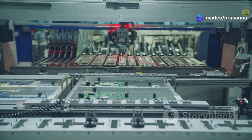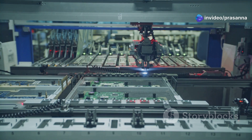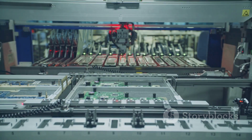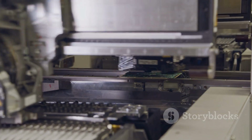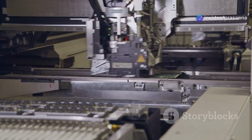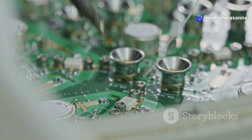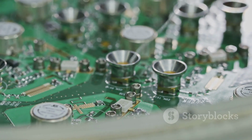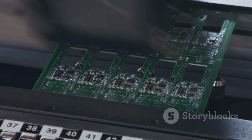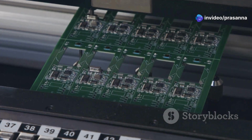Modern manufacturing facilities utilize high-speed pick-and-place machines, guided by vision systems, to accurately place components onto the PCB. There are two main methods for attaching components to the PCB: through-hole technology and surface mount technology. Through-hole components have leads that pass through holes in the PCB and are soldered on the opposite side. SMT components, on the other hand, are mounted directly onto the surface of the PCB, offering a smaller footprint and increased component density.